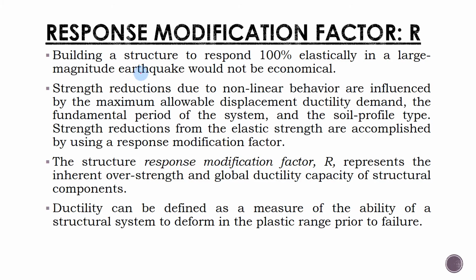Okay? Strength reductions due to nonlinear behavior are influenced by the maximum allowable displacement ductility demand, the fundamental period of the system, and the soil profile type. Strength reductions from the elastic strength are accomplished by using a response modification factor. Okay, the structure response modification factor R represents the inherent overstrength and global ductility capacity of structural components.